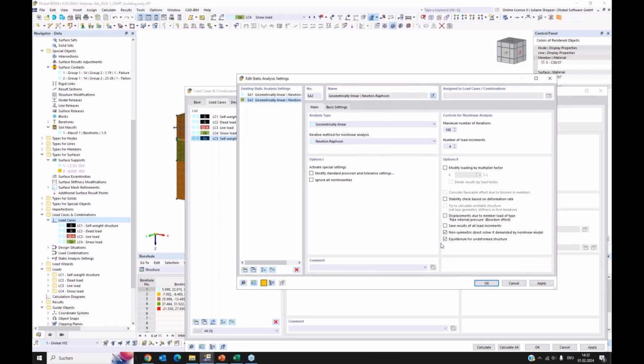With this setting, our structure is solved, it is loaded, and the stress state is calculated, and the deformations that are calculated are reset to 0. That's why we write for undeformed structure. So this is perfect for our initial state. I will rename it so I can understand later more easily.